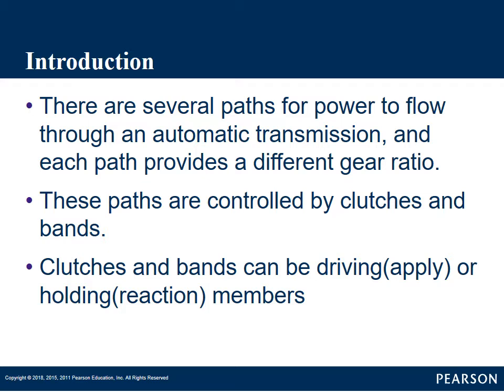These clutches or bands can be driving or holding members. The driving, often called apply members, and the holding are called the reaction members. Remember, if we think of our planetary gear sets, we are going to hold one member and we are going to drive another member.